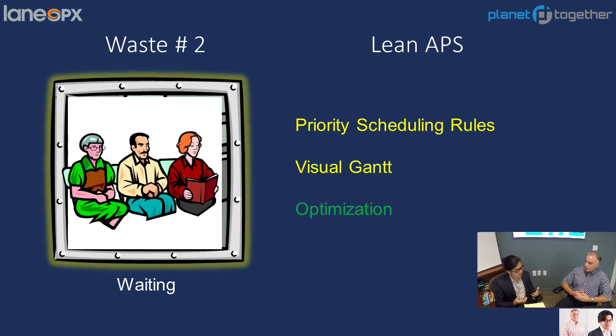Right. So in a world where you're stuck using a spreadsheet or whiteboard, you really have no visibility as to the relationship of various work orders that have interdependency, whether it be multiple operations or web items. And so with a system like advanced planning and scheduling, you really get to see the visual relationship, the interdependency, whether it be materials or process, especially machine shop operations. You really have, down to 14 operations, 15, and so forth. We really need to sync them all together so they all flow in a non-stop manner. So through the use of optimization, you can set a priority to make sure to minimize the idle time between operations.